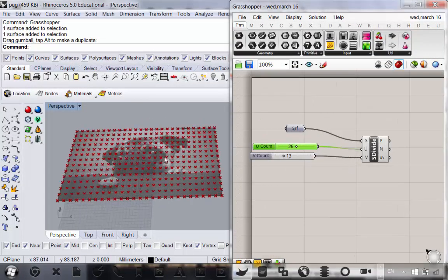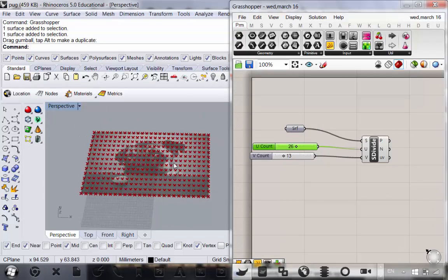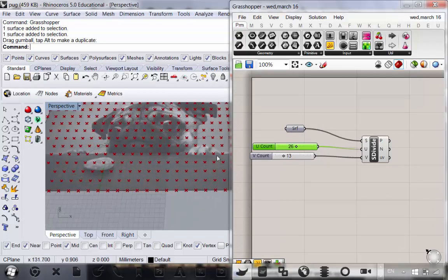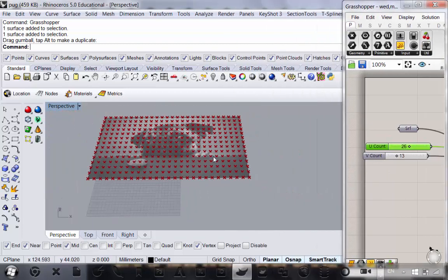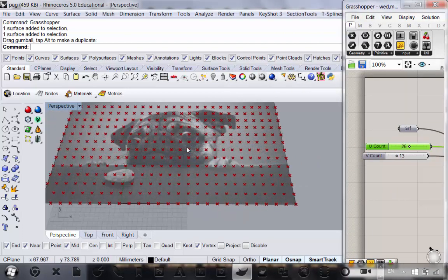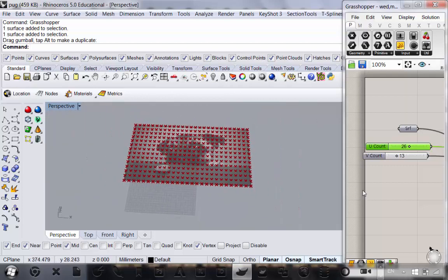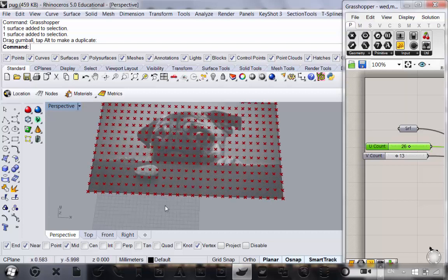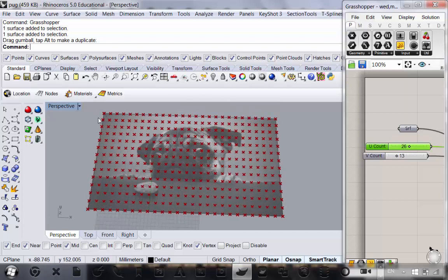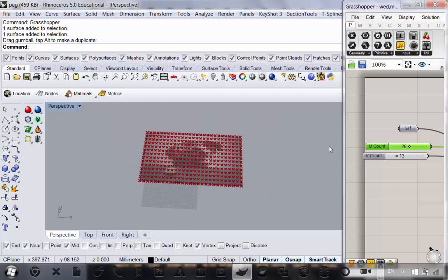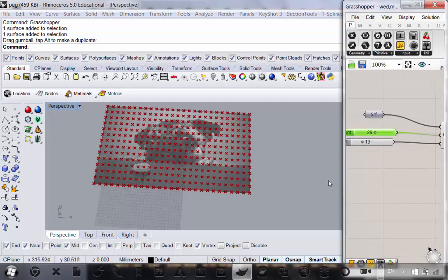Essentially, the way image sampler works, that's the component we're going to use, is it's going to sample this image based on some value. You know how in an RGB image, there's certain things. There's our R value, red, green, and blue together, like 255, 255, 255 equals white, 0, 0, 0 equals black. We can also measure brightness, as well as some other things. Image sampler takes this image and samples those values at these points to return a number. We're going to see how that works.